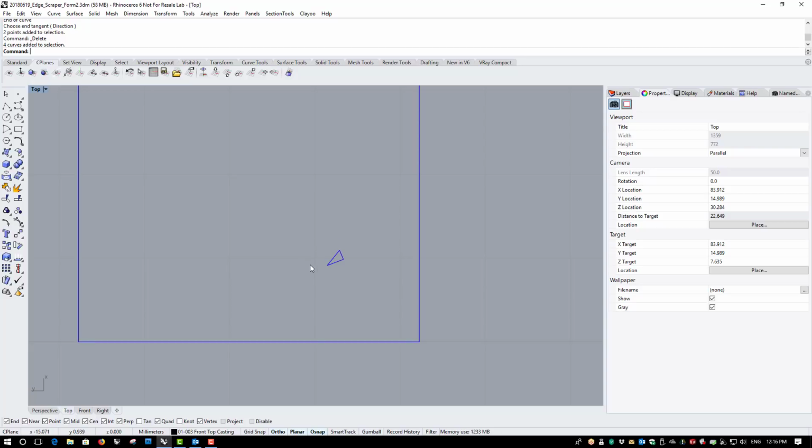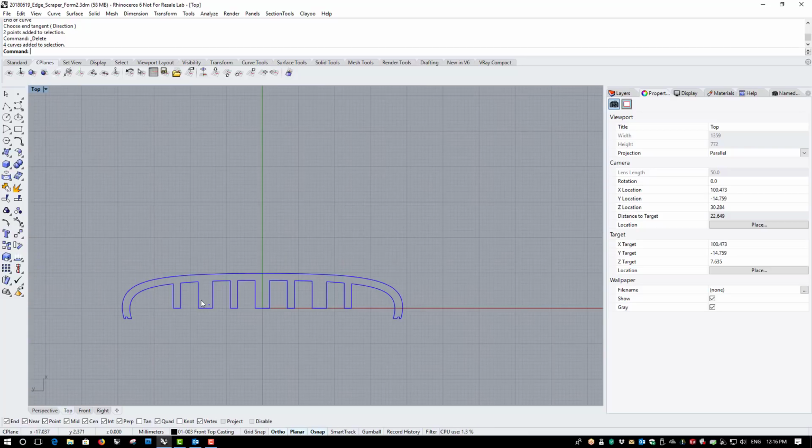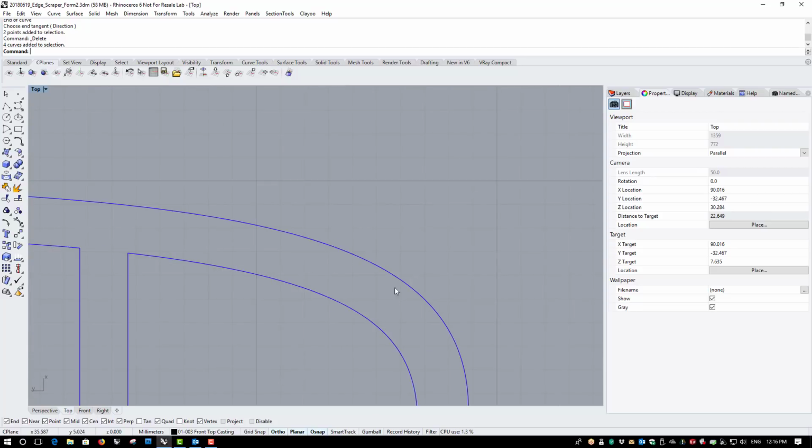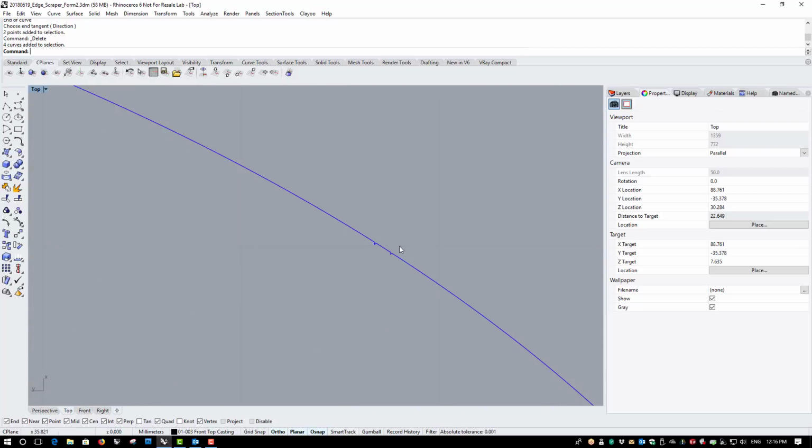And so if you have a portion of surface that may have been created by some trimming or by something that hasn't been deleted, and this sits inside the volume that you are creating, then this will cause the STL file to fail. The third reason why STL files commonly fail is by having a non-manifold edge.